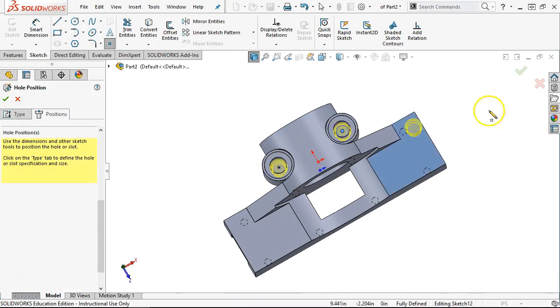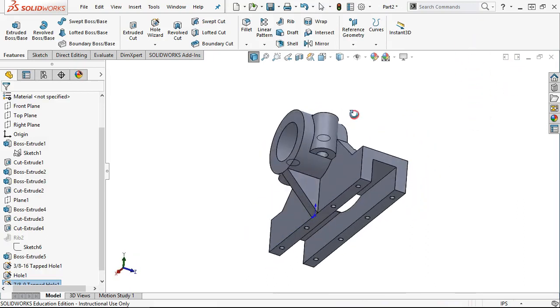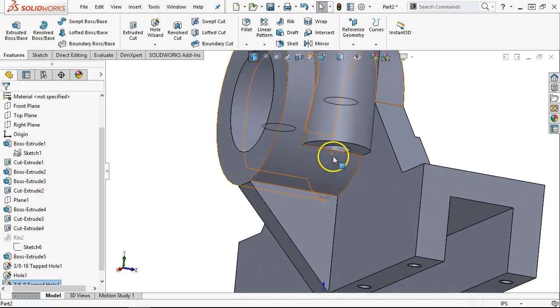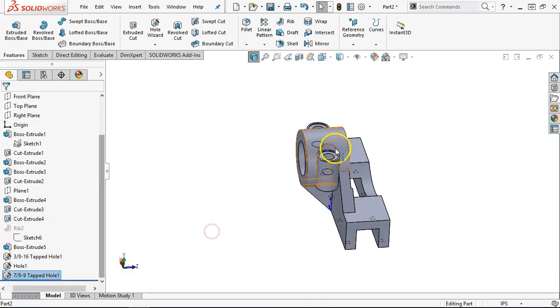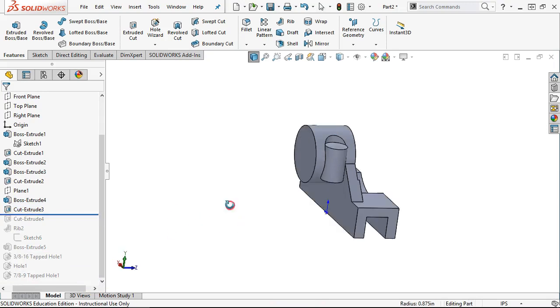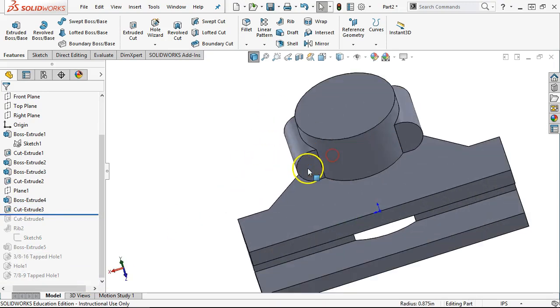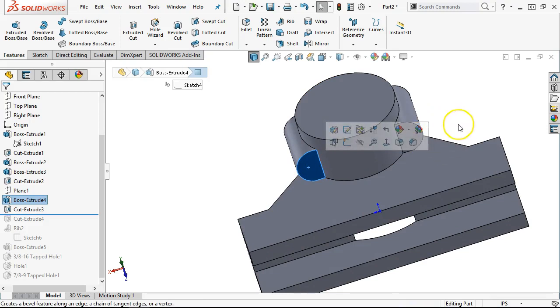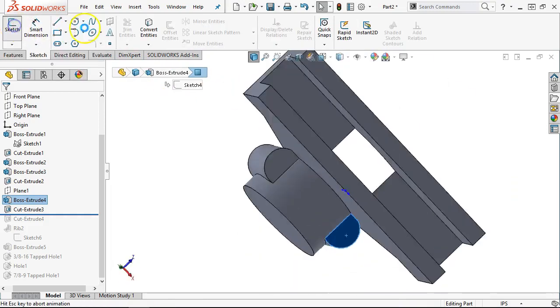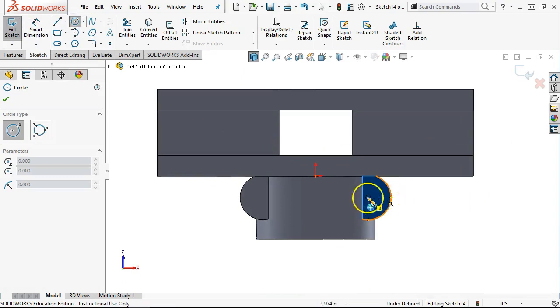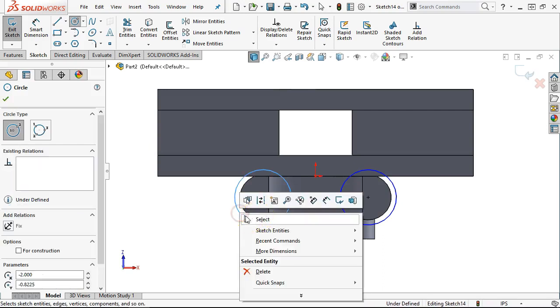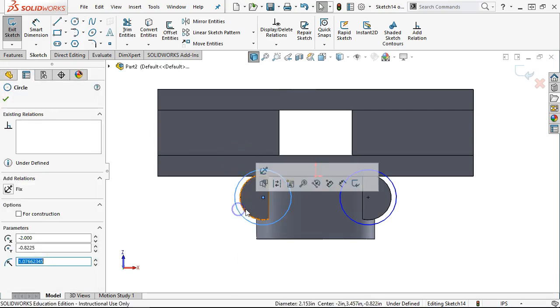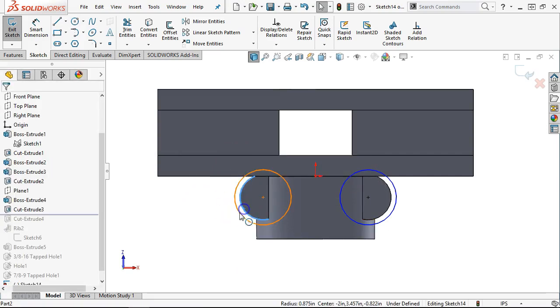All right, so finding our centers. And since that breaks through and doesn't quite come to a cylinder, we'll need to roll back and pick up that geometry. All right, so this was about there. So grabbing the rollback, since I already have that geometry in place, we'll open up the sketch. The converting was okay. I think I like just having the circle, and we'll make those co-radial.